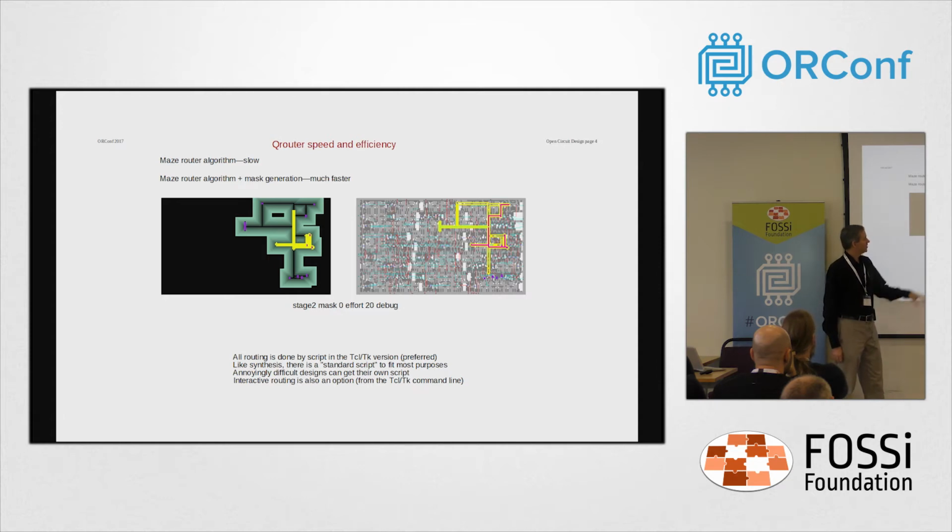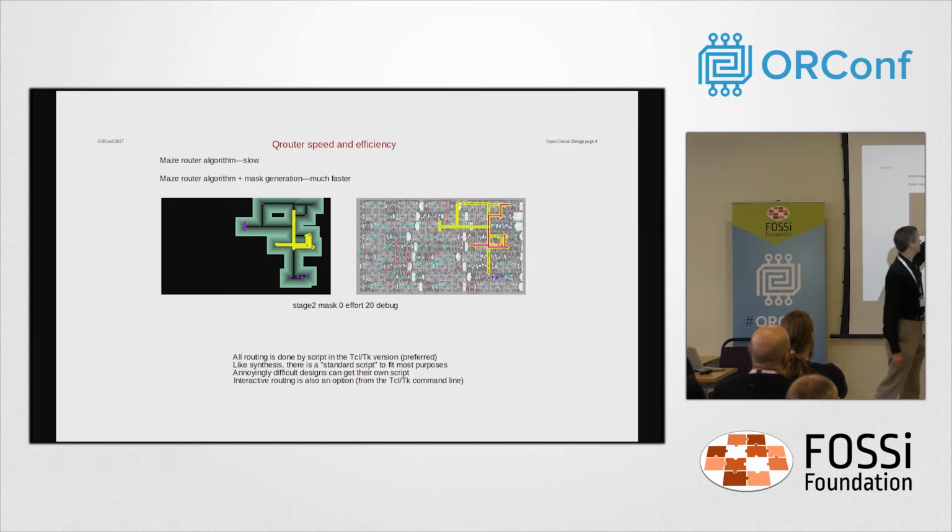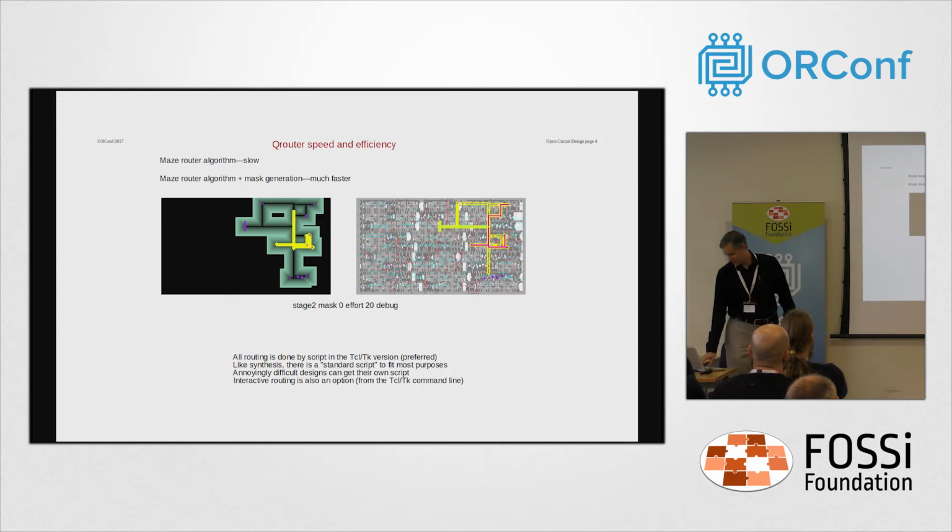So the best thing I did for that was to create the idea of building a mask where you want the route to go. So I build out a trunk and branch system for a set of nodes and say follow that. This little shaded region shows that it's going to follow the innermost path as the ideal, and then as it fails to find that, it'll spread out until it finds something in this area. By restricting the amount of space you're looking for, you can find the routes very fast compared to having the entire space available to be searched.